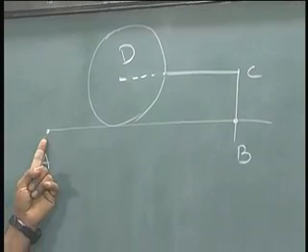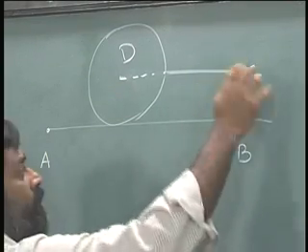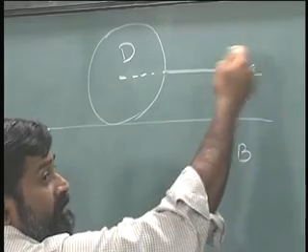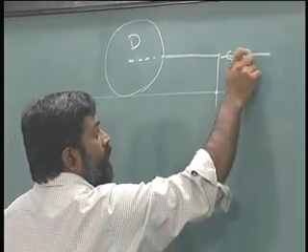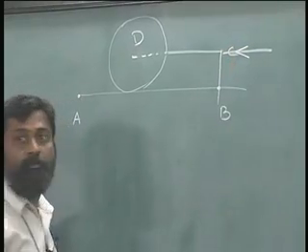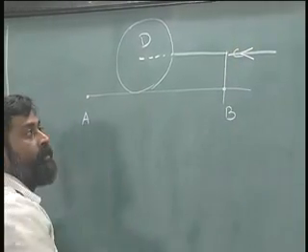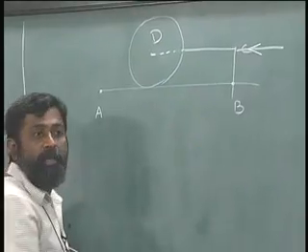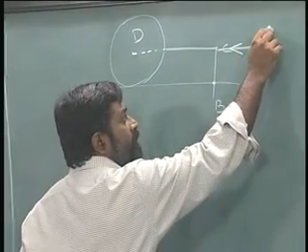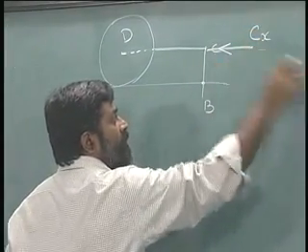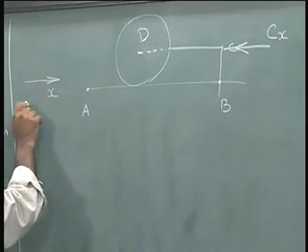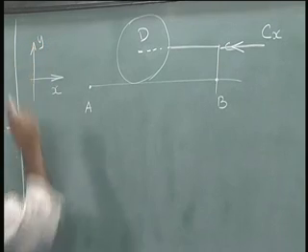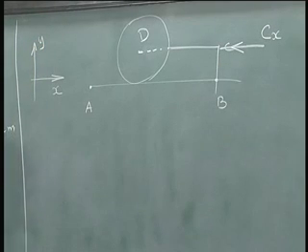Now what all have we removed here? We have removed the support that restrains motion in the horizontal direction, which means I should have a reaction from the fixed frame onto this system of planar rigid bodies. So let us call this Cx, along the x direction. We are going to take this as x direction and this is y direction, for our own convenience.